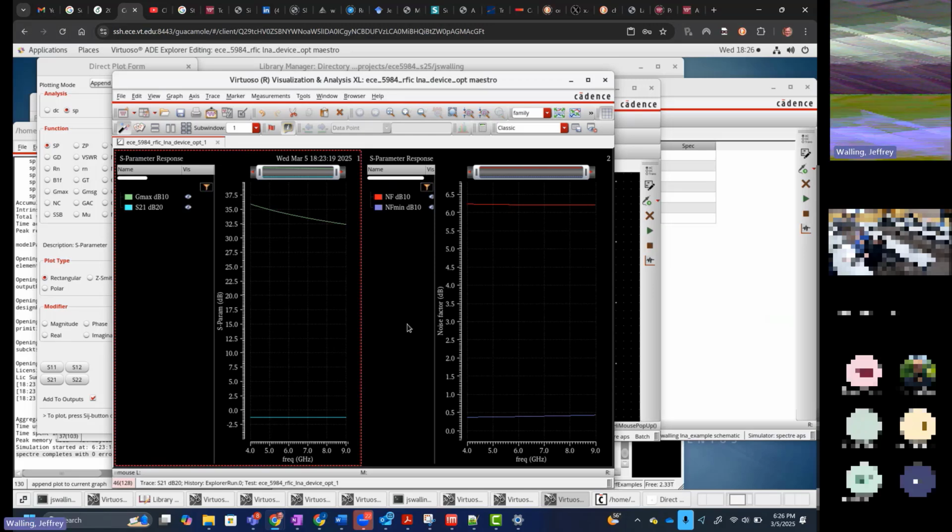Well, the device itself has a noise model internal to it. And then there will also be some attenuation from the network that's happening. So it's taking into account all of those things. It's more or less doing the same calculation that you're doing on your homework this week for the various amplifiers in part 1 of the problem. It's finding how much output signal I'm getting with all noise sources included relative to how much I'm getting when I only include the source resistance.